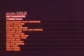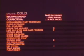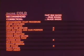If the engine starts, goes to fast idle, then slows and idles rough with lots of black smoke, it's probably running over rich. Here we make sure there is no binding anywhere in the choke linkage and check for proper vacuum kick and fast idle system operation. The EGR valve must remain closed and sealed properly.